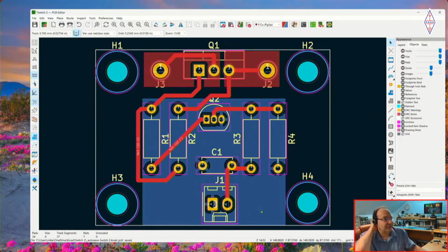But yes, that's right. Sorry Mike, just to interrupt again, but we're trying to make this interactive with everybody at home. Alan M7ASJ has made a mention of something you might want to cover now, and says, what about heat sinks? Because of course you could use the copper to act as a bit of a heat sink as well. You can, and you can use filled zones as a heat sink as well.